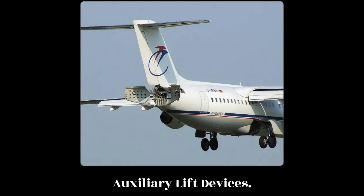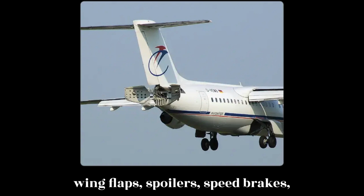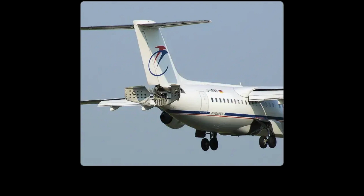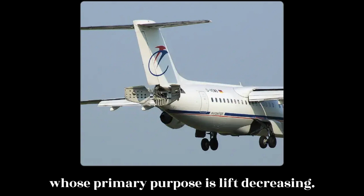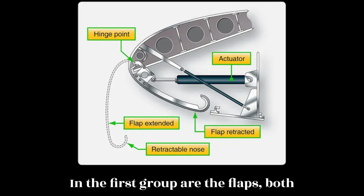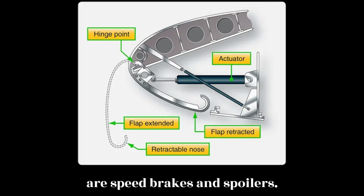Auxiliary lift devices. Included in the auxiliary lift devices group of flight control surfaces are the wing flaps, spoilers, speed brakes, slats, leading edge flaps, and slots. The auxiliary groups may be divided into two subgroups, those whose primary purpose is lift augmenting and those whose primary purpose is lift decreasing. In the first group are the flaps, both trailing edge and leading edge, slats, and slots. The lift decreasing devices are speed brakes and spoilers.